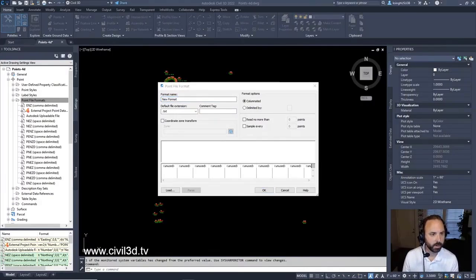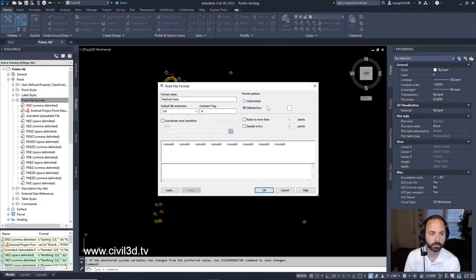I'm going to enter in some information here. I'm going to type in manhole data. For the comment tag, I'm going to put a hashtag in here. Then for format options, I'm going to select delimited by. It's going to be delimited by a comma.